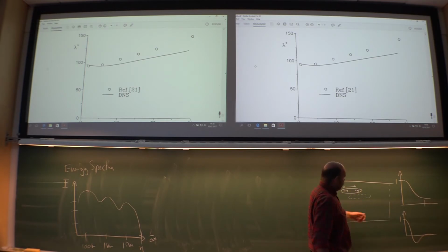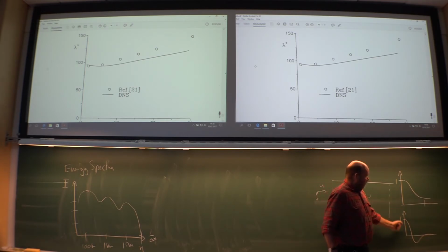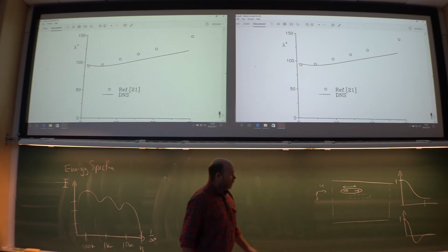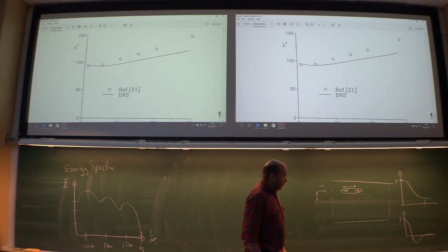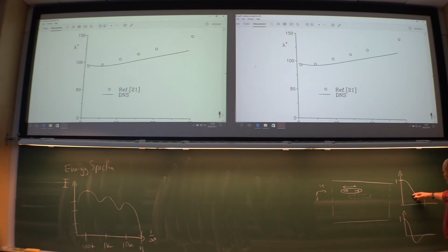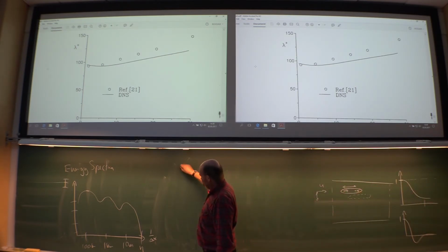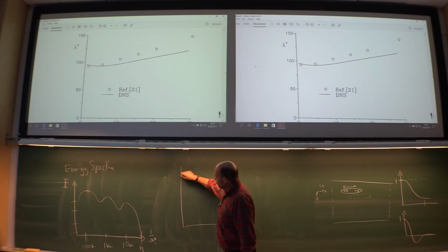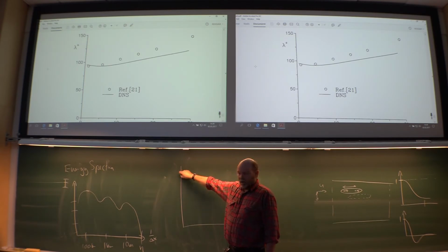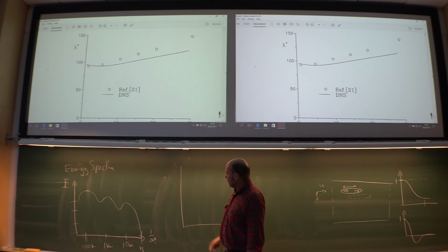What about these two-point correlations here? Well, if you do a Fourier decomposition here, the biggest energy you get, say for the streamwise correlations, will be that you have one wave that is infinitely long. So from that first figure, I would assume an energy spectrum with the biggest energy where you have infinitely long waves. So it should go something like this.